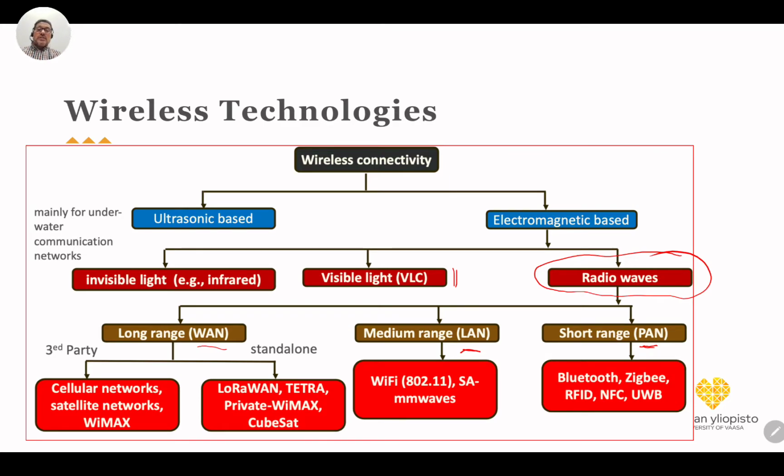It uses millimeter waves range, so it is more than 30 gigahertz, and because of the high frequencies at that range, the penetration of that wave is limited, and also the coverage behavior is quite limited. So its more visible application will be in the medium range, like in airports, and, for example, one big corridor in a company or something like that.